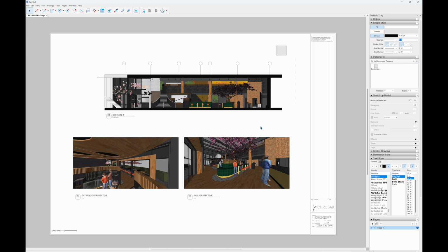So you would have to create your tags, and to create the same level of complexity with my layers in AutoCAD here in SketchUp, I would have to create so many more tags to try and get that visibility to work for me. It just wouldn't be worth it. So that's probably the main reason, but it's really just a technical reason for complexity.